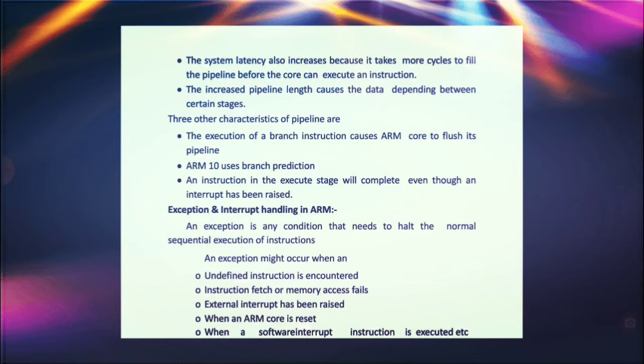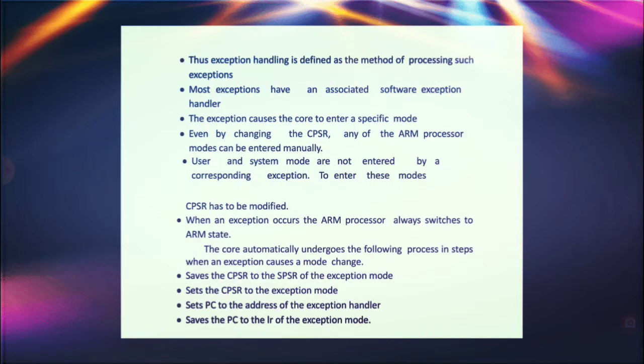An exception might occur when an undefined instruction is encountered, instruction fetch or memory access fails, an external interrupt has been raised, when an ARM core is reset, when a software interrupt instruction is executed, etc. Thus, exception handling is defined as the method of processing such exceptions.